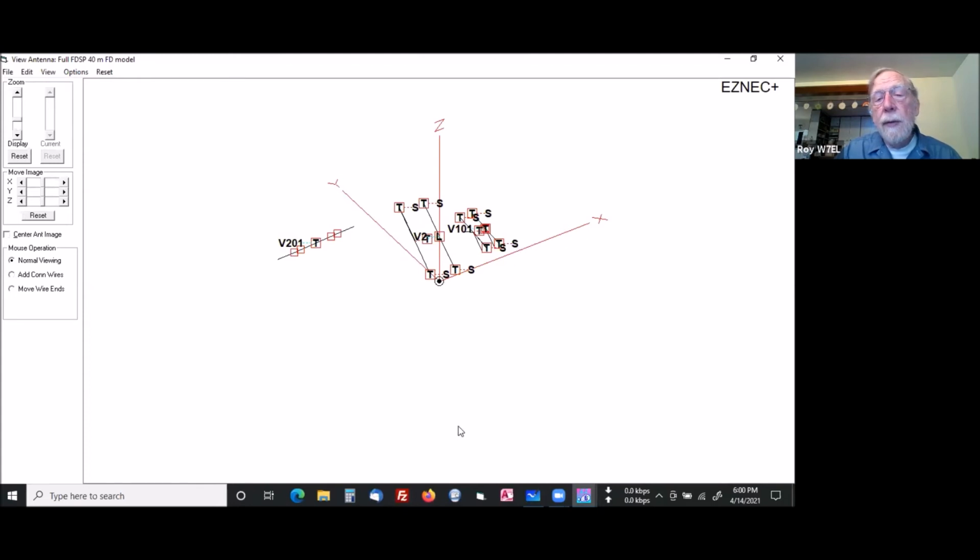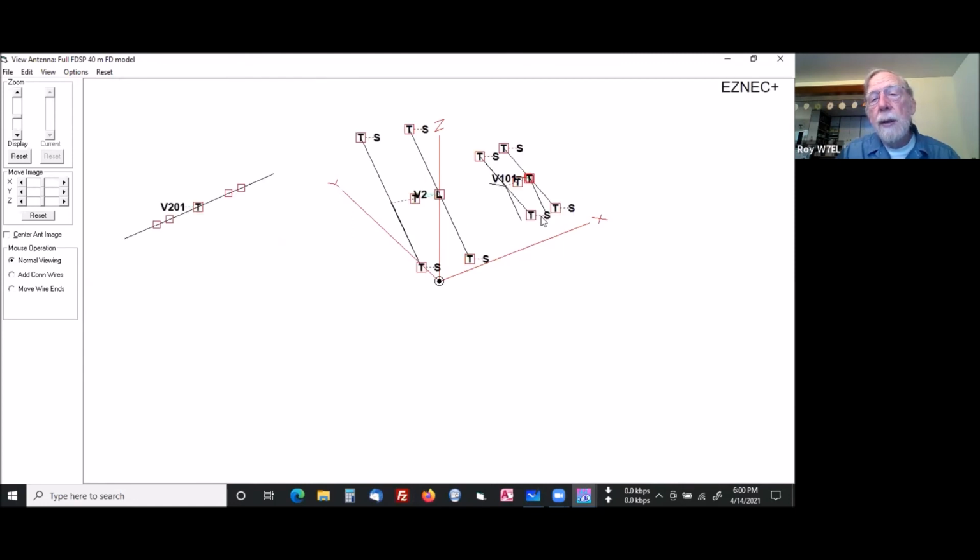And let's see if I can zoom here. I'm sorry, this is another Field Day special. This is a 20 meter Field Day special. And what I've got under here is an element for 15 meters. It's a 2-element inverted V Yagi. And then I've got a matching arrangement at the feed point so that it matches both antennas.